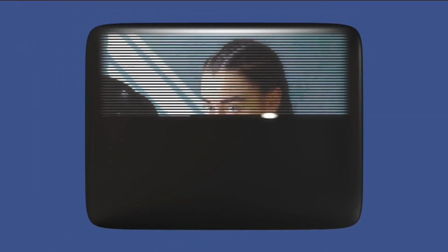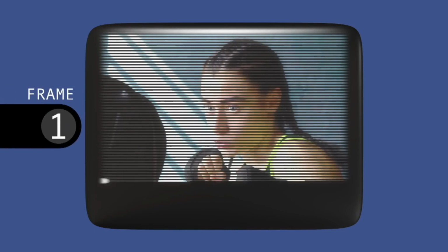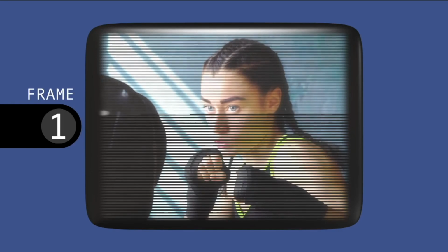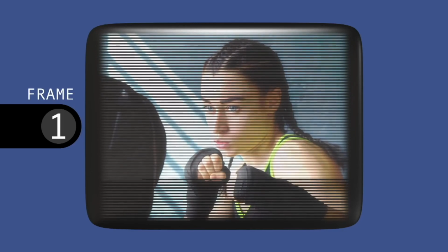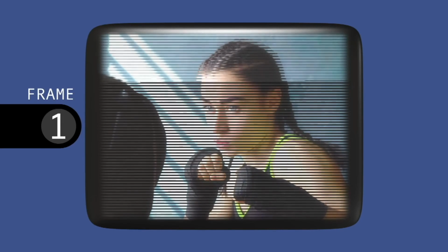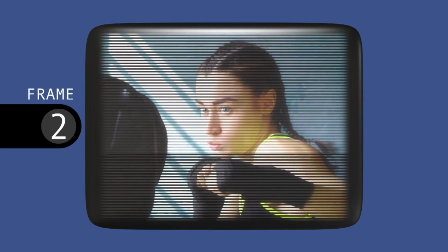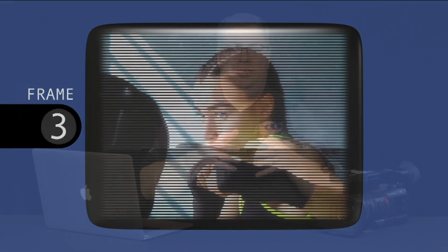The solution? Draw every other line to get across the raster in half the time, then go back and draw the missing lines in a second pass. That way the refresh rate is doubled, and even though only half the resolution of the image is on screen at one time, the swap is so fast that persistence of vision makes it look like a full resolution frame. So now you understand the concept behind interlaced and progressive.